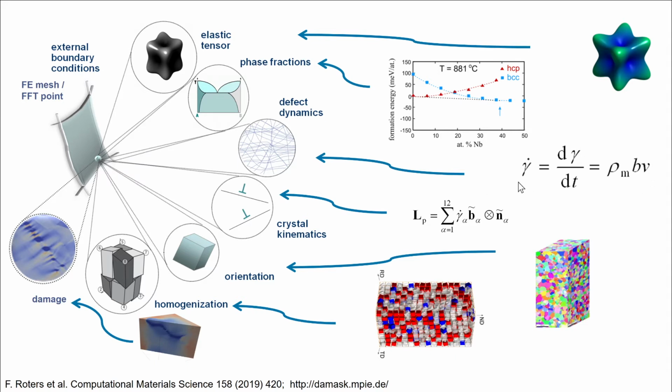And we have here a coupling between the local microscopic shear rates and these internal shear carriers that I've mentioned before. This is the kinematics that I've shown you on the slide before, how we now translate this into the local orientation factor, which is a dyadic matrix of the Burgers vectors and these plane normals, also often referred to as the Schmid matrix.